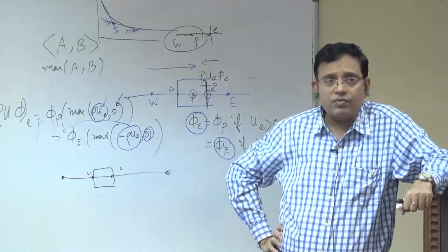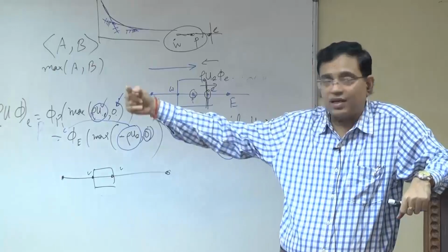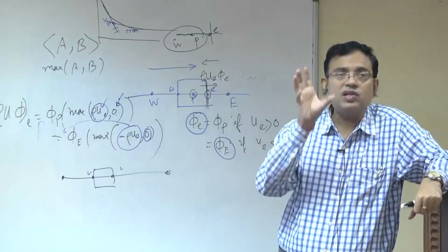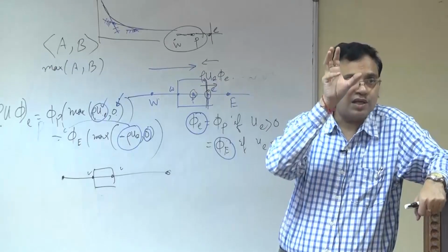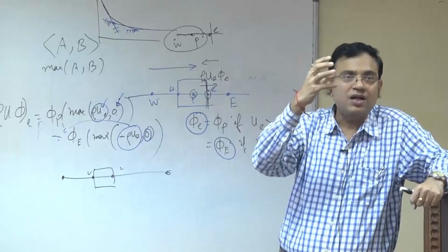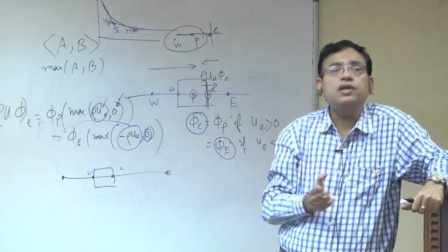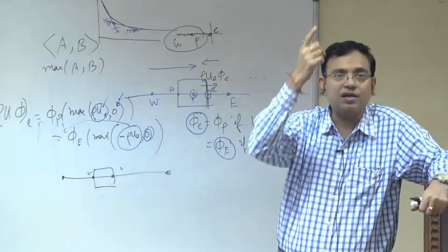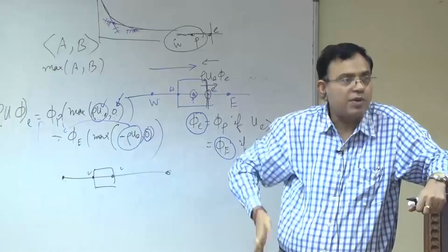But in reality, when it is in between, it is exponentially represented in a nice way, but exponential calculation is computationally expensive. So, there may be more simplified forms of doing it through other forms of interpolation. One is the piecewise linear, which is the hybrid scheme, and representing it by a power law is the power law scheme.